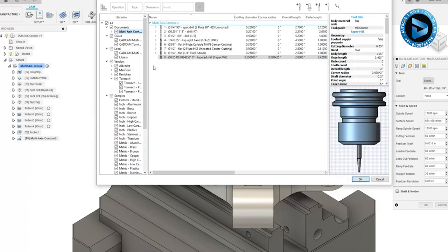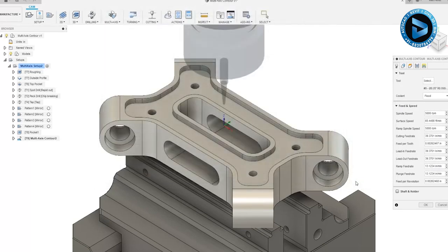We're just simply creating this to explore these toolpaths, and again, I can't stress enough that the tools that you create or use need to represent a real tool. So if you're not downloading them directly from your manufacturer and creating your own tool library, you need to make sure that you use the tool creation and replicate everything that you have. If your tool supplier doesn't supply a CAD file for the tool, then you should have all the parameters on their website that you can populate and create a representation of it. From here, we're going to select OK, and now we have a tool that we can use.